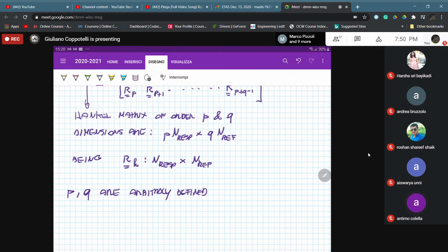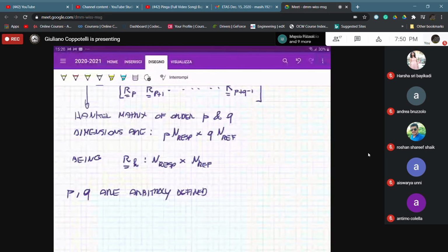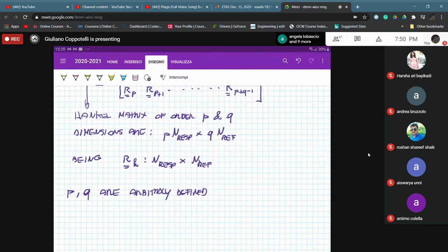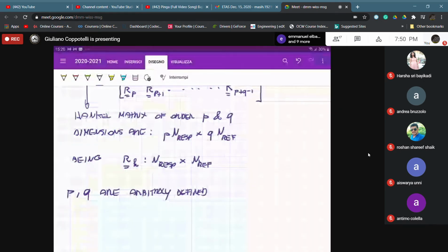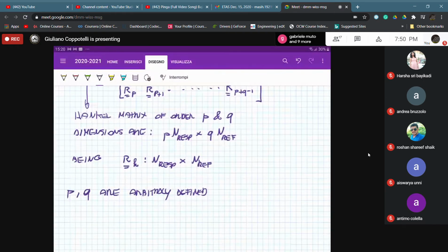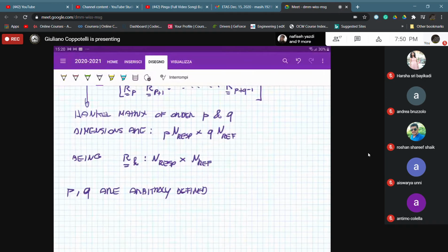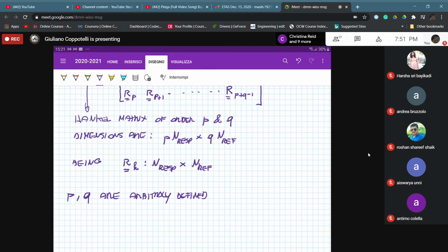Reference points are those measuring channels that you consider to build your correlation functions, so you have to consider two channels in order to build a correlation function. Those reference channels are defined upon the most important channels in your measurement. For example, if you are considering the vertical bending of a flying wing, maybe you can have one reference channel that is the output acceleration at one point at the wing tip.